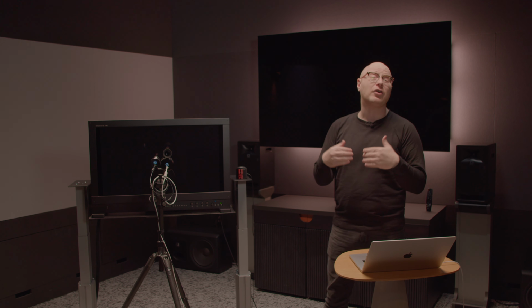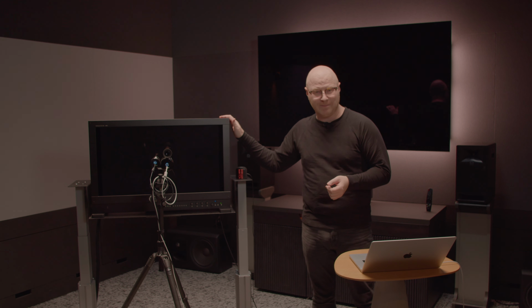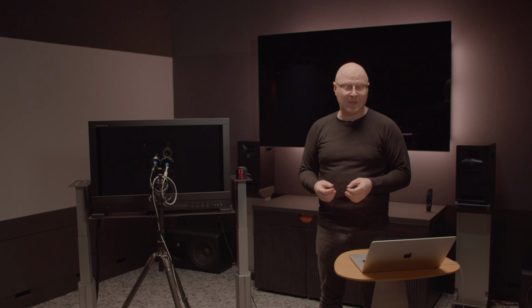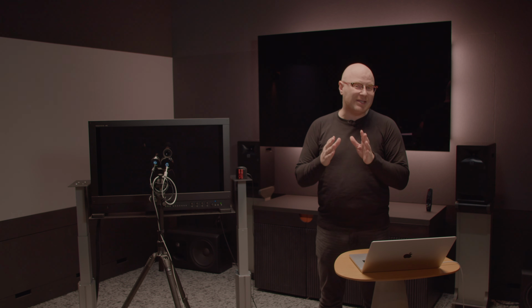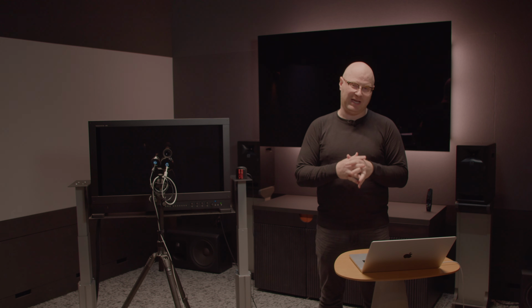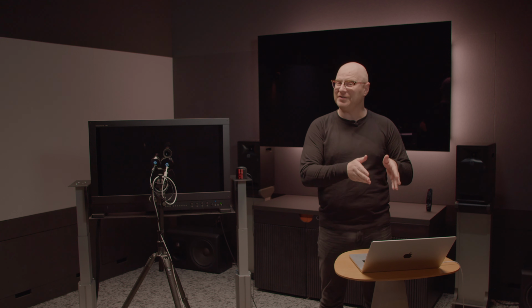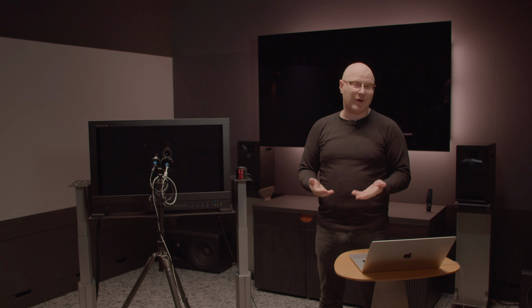While we're measuring the color checker, let's take a moment to discuss alternative white points when calibrating the Sony BVM-HX310, the history of which comes from legacy calibration methods. In the past, we used CIE 1931 as the model for our color matching function, as well as D65 as the white point. This is the standard that we still use today.